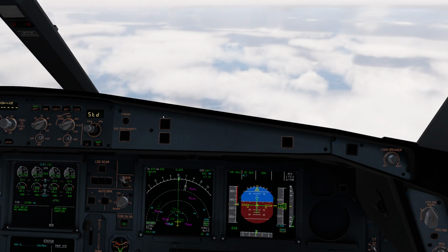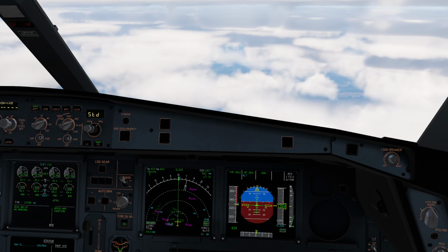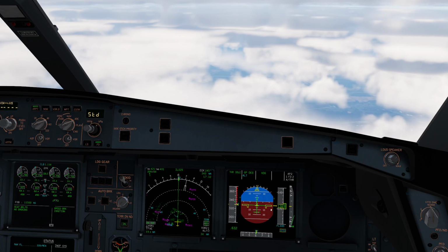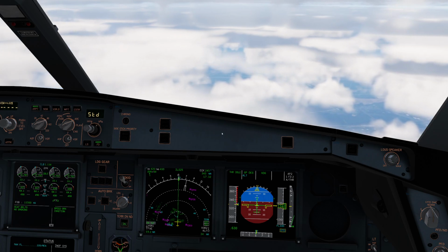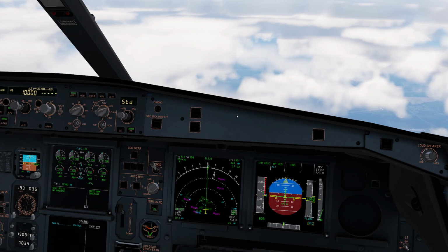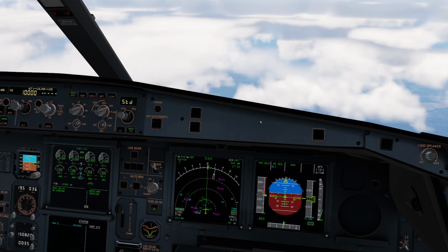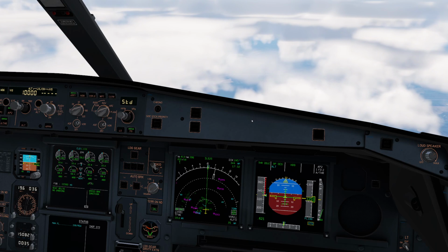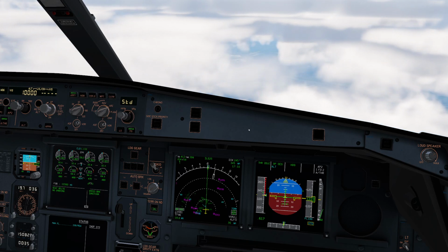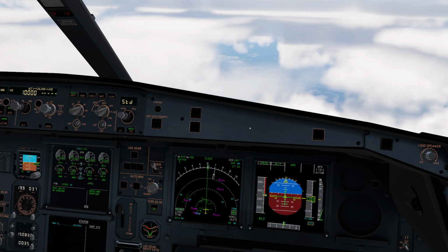Now, as we are approaching flight level 100, we can slowly make sure that we are reaching the altitude smoothly. So from about 12,000 onwards we can start retracting the speed brakes, and then finally level off, reduce the speed, and get off the oxygen masks. It's a little unfortunate that right here in the simulator you don't have the breathing sounds.